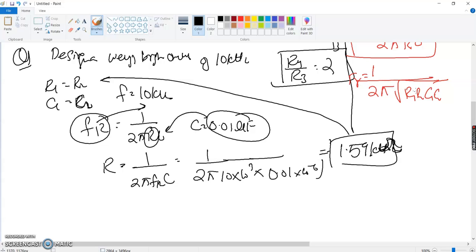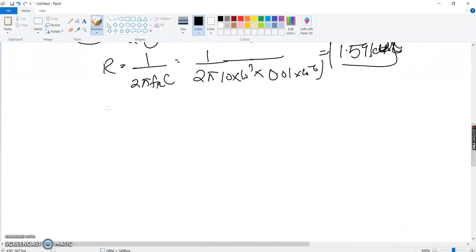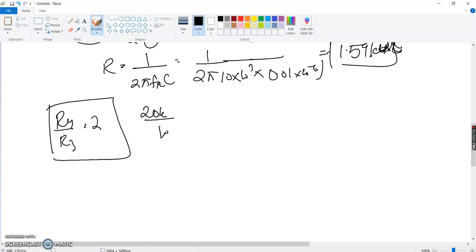We have done a lot of the circuit, right? We have figured out the beta part, C1, R1, C2, R2. Now the only remaining part is the gain, which is pretty simple. We have already concluded that R4 over R3 should be just 2 because of the circuit, right? So I can use a 20 kilo ohm and a 10 kilo ohm resistor to get a gain of 2.